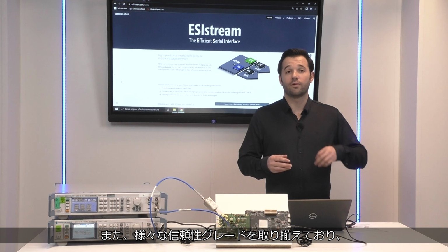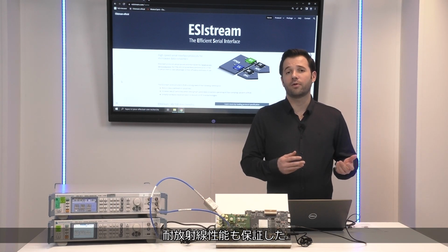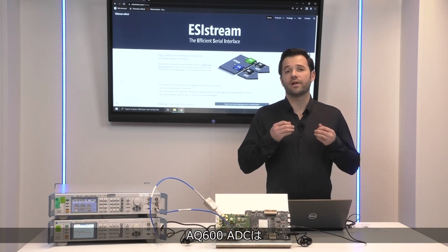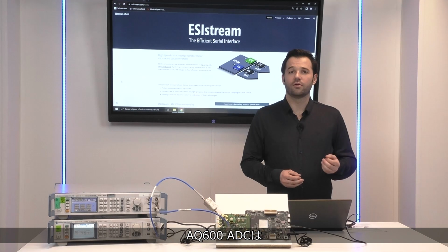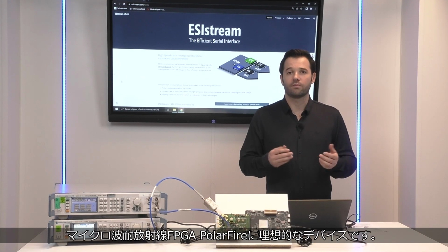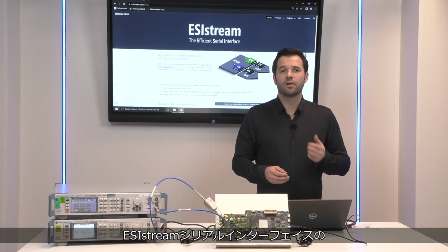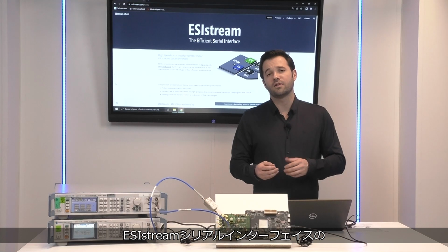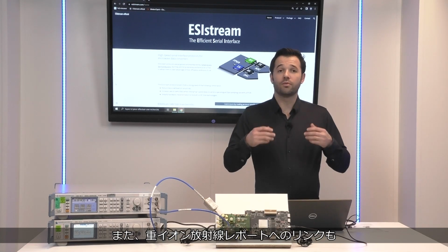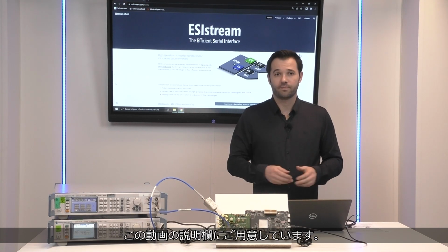With a choice of various reliability grades, including a radiation-tolerant and QMLY space-qualified version, the AQ600 ADC is an ideal companion to the Microchip radiation-tolerant FPGA PolarFire. Extensive testing has confirmed radiation tolerance of the EasyStream serial interface used to transmit samples. And a link to the heavy ion radiation report is available in the description of this video.